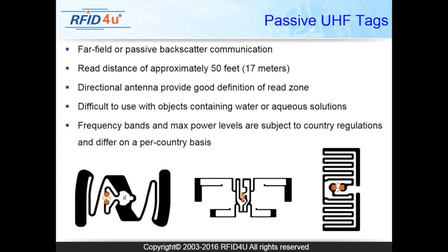And then the different power levels, based upon the amount of power that you give to the antenna, will establish what your read range is, tied obviously to the tag. But because of interference with the bands that are next to UHF, the countries have also limited or changed the power, specifying the power settings that can be used for each of the different countries.